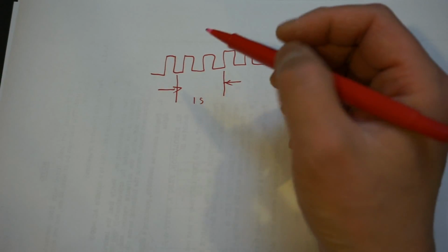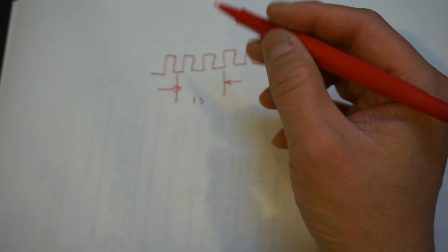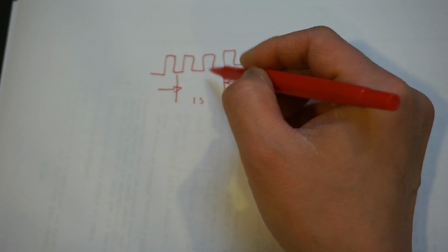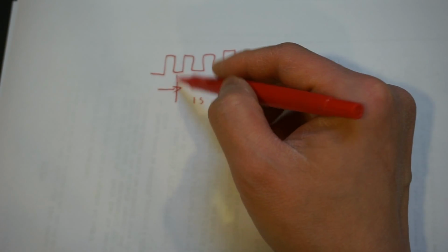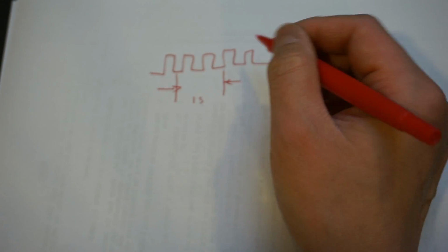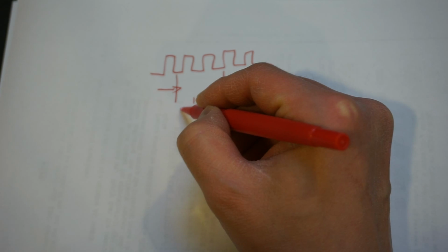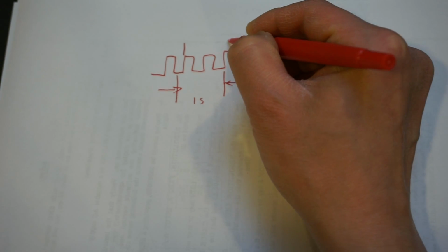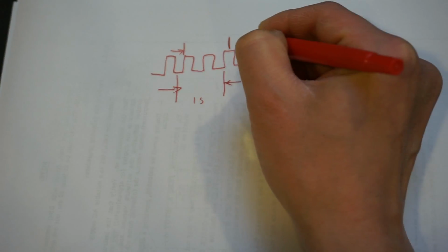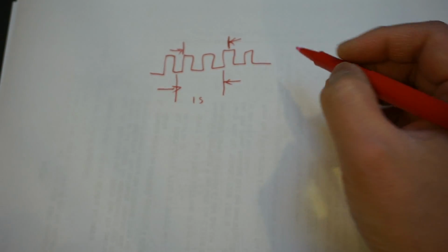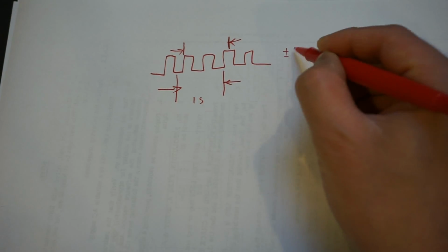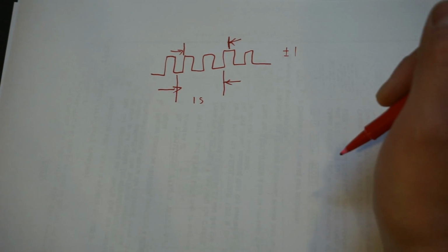Now this is very intuitive, but it does have its drawback. As you can see, the first thing is that it depends on where the input pulse lands in terms of your gate opening and stopping, and you could count a different number of pulses. In this case, for example, if I open the gate slightly later, then I would actually start here and end here. So now instead of 2 pulses, I would have counted 3 pulses. So this is the classic plus minus 1 count error.